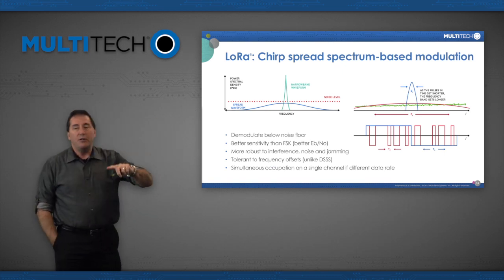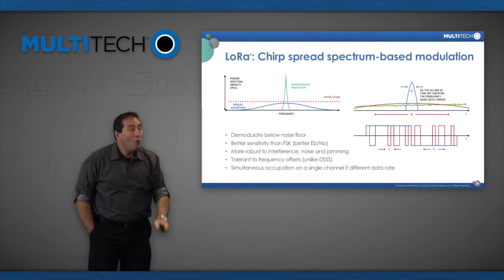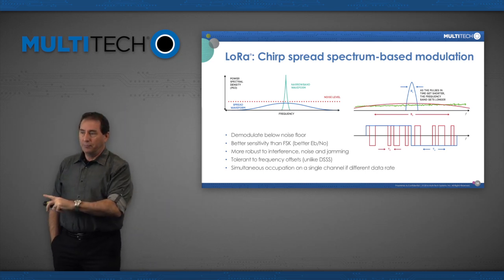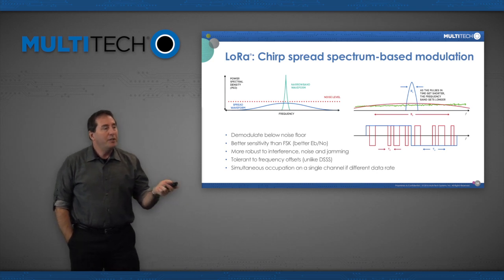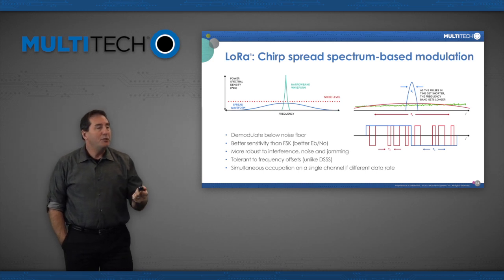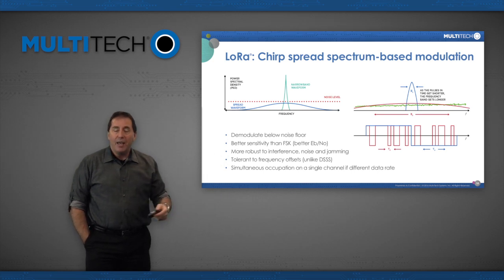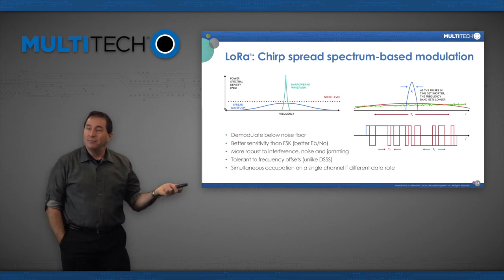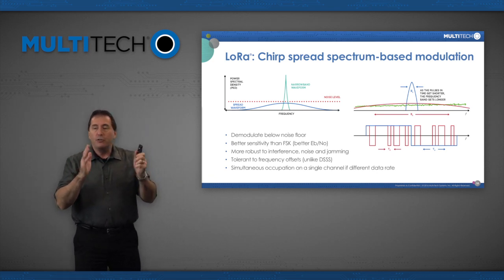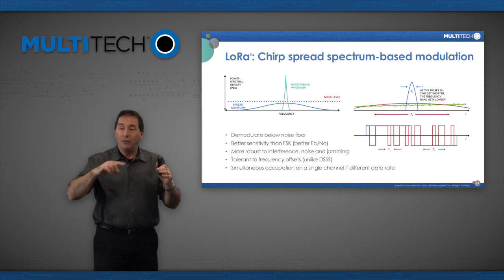So at the lowest level, let's start with the radio, okay? LoRa is actually a fairly old technology. In fact, it is so old that all the original patents have expired. It kind of came out of the military and intelligence services, where they wanted to be able to communicate over a long range, reliably, and not be listened into, right? So what did they come up with? They came up with a signal called Chirp. Chirp is just a way of modulating a signal in bursts without having a carrier wave.